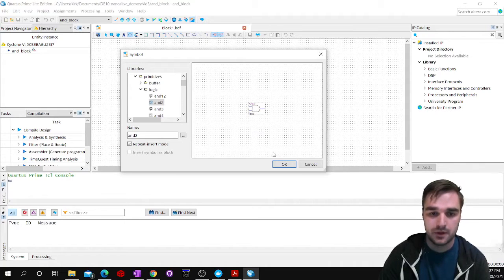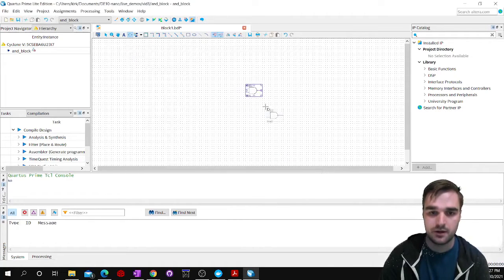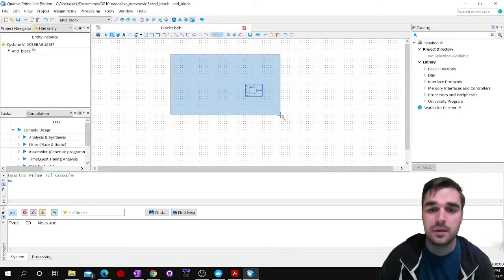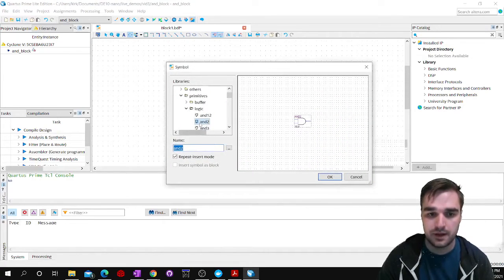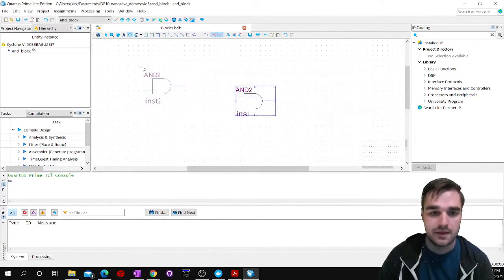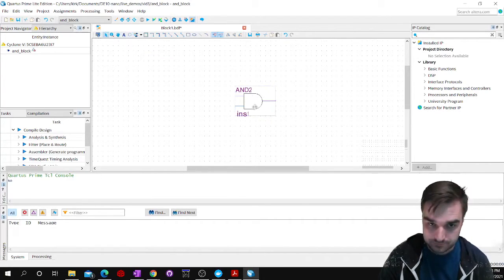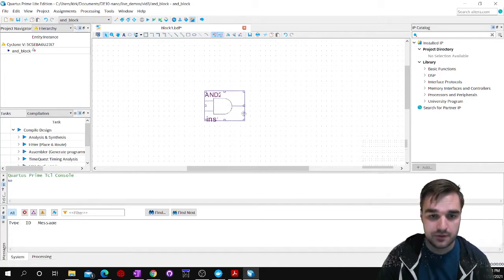Okay. So I'm going to click OK, and I'm just going to place this down, and I'm going to zoom in on it. I think that might be helpful to make this a little bit bigger. So again, I went up here. This window pops up. I select the AND gate. I click OK, and then now my mouse is moving around. You just click and plop it down. It's basically like Legos. I'm going to switch my tool here from the logic symbol tool back to the selection tool, and that's going to let me click this and move it around. So we have this AND gate.